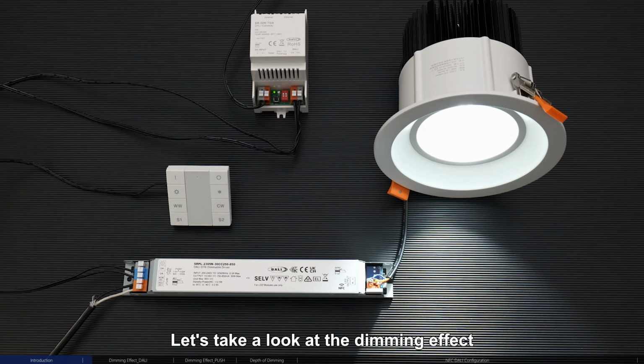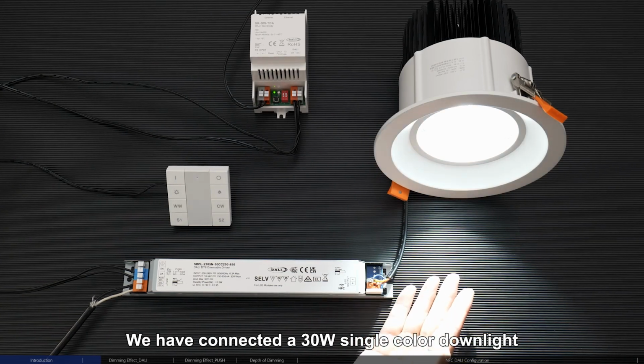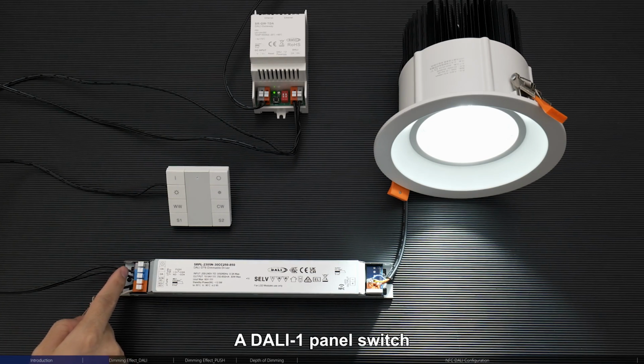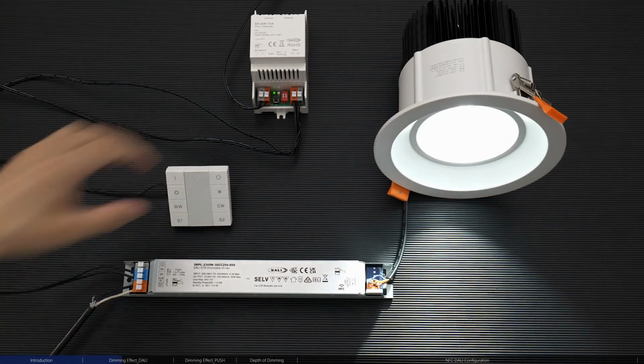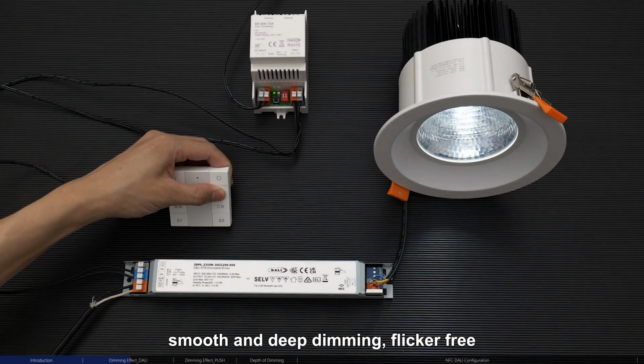Let's take a look at the dimming effect. Works with DALI devices. We have connected a 30-watt single-color downlight, AC power input, connected to the DALI bus. A DALI 1-panel switch. Off. On. Reduced brightness. Smooth and deep dimming, flicker-free.